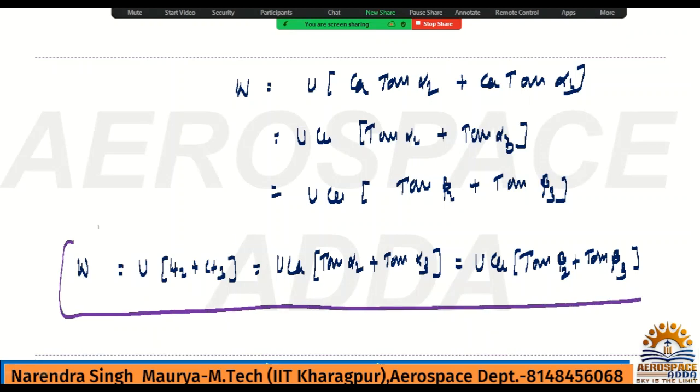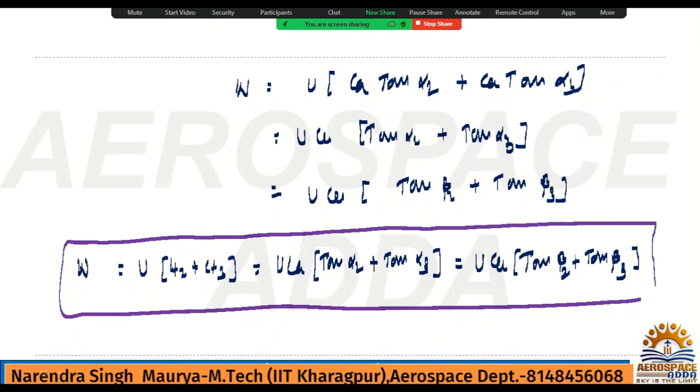Okay, you forget everything, no problem. You need to remember the velocity triangle as well as this formula, because nowadays they are giving the velocity triangle. In a few questions, if you check compressor or turbine, they had given a triangle. So that's the reason you need to learn the velocity triangle. They have given values, so you need to understand, okay, this is CT2 or CT3, or this is C1, C2 or C3, or W1, W2, W3, what is alpha 2, beta 2, all those things.